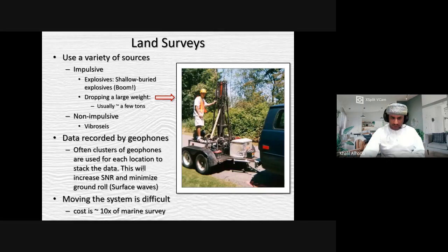My point here again, I want actually to put more than one geophone. It has certain impact. You increase the signal. And another thing, making an array of geophones, not a single geophone at one point, is very effective at removing ground roll. What's ground roll? It is surface wave. Why do they name it ground roll?